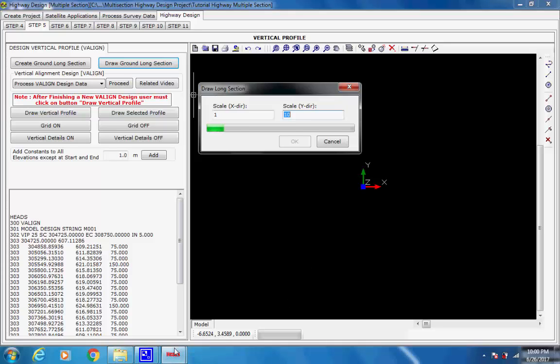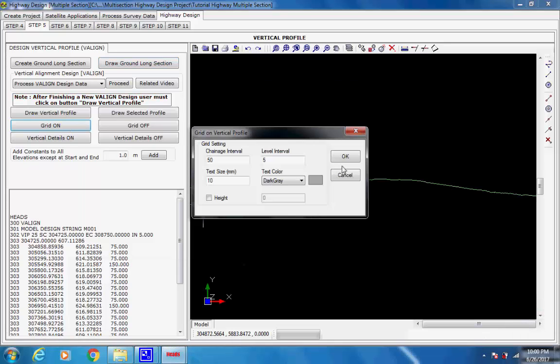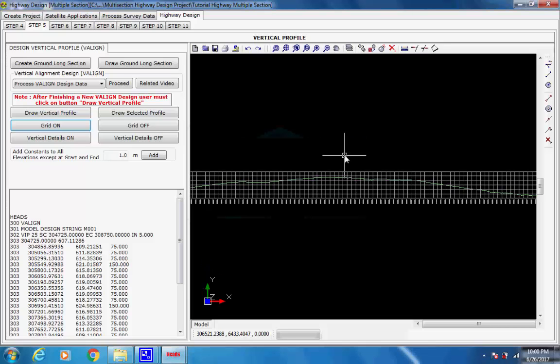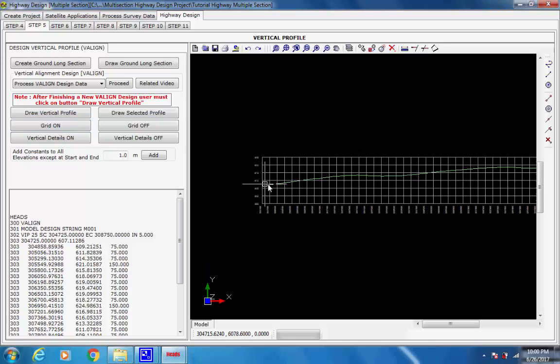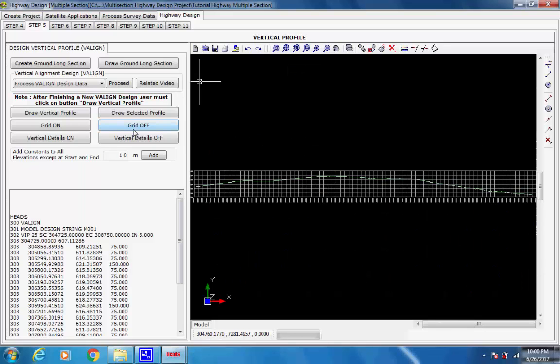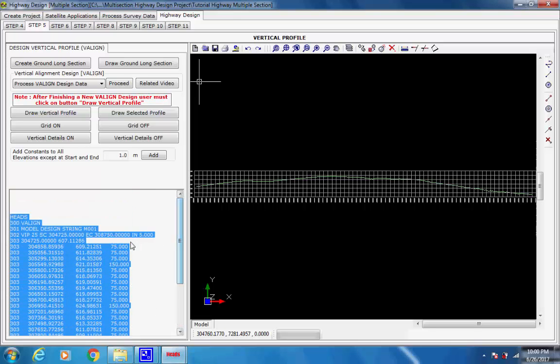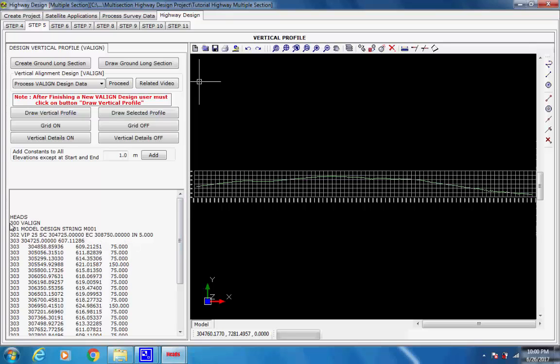In this session we're processing tutorial example data, so from the project data file we have the data for 300 V-align as shown below in the project workspace. The new interactive V-align design was described in the last session, by doing the design of vertical alignment, not described here. In the similar way, if we design a new vertical alignment, then we have the design report file valignment.rep. At the end of the report there was 300 V-align data which we can copy and paste in the left panel of the workspace.